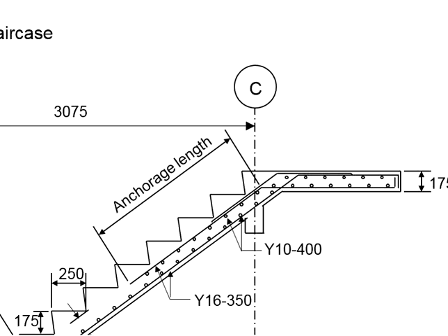when it is in a straight line, as it is used to carry tension. When the reinforcement is embedded inside a member, the top priority will be ensuring the reinforcement is in a straight line as long as possible. For this main reinforcement, the longest span that you could go will be nearly to the end, where it must bend so that it fits nicely into the flights. In this case, you will extend the reinforcement and start bending here.